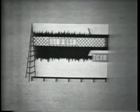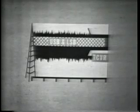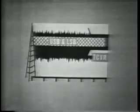So our receiver has given us an effective gain of 2. This has increased the system's effectiveness by a factor of 6. Eliminating one sideband reduces the used frequency space by half. This increases the number of frequency channels available, and shifting the power of the carrier to the remaining sideband tripled the effective power of the transmitter.